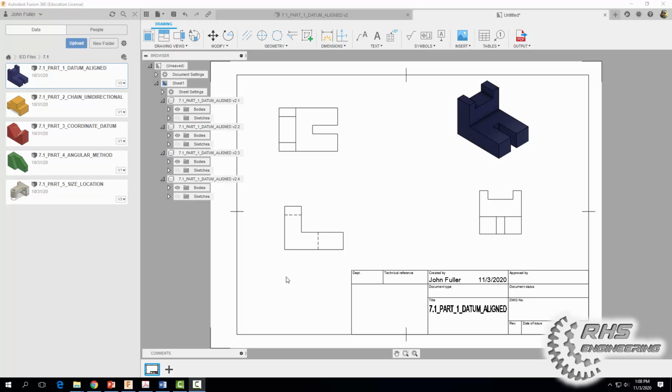So when we do datum dimensioning, it's customary to start from a point and work your way across feature to feature. So I'll select this point, and then I'll come to this line and dimension up, and then I'll keep working across. I'll go from this point to the next feature over to this point and then up. So let's go ahead and do that. Come on up to dimension. We'll start from our datum, from this corner to our next point or feature, and move our mouse up. Same thing, we're just going to keep working our way across. We're going to go to our datum again and then work our way across, and then click again, drag your mouse up, and there you go.